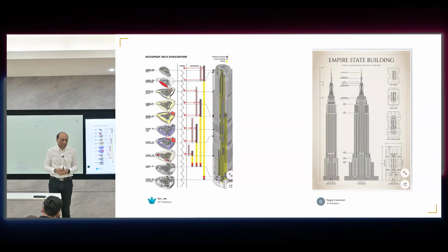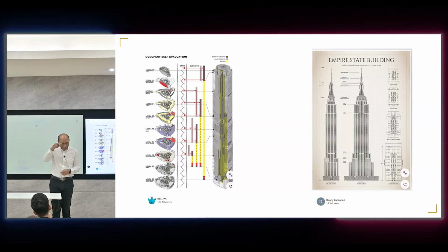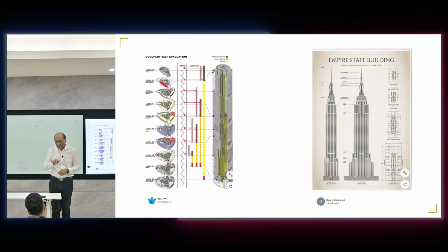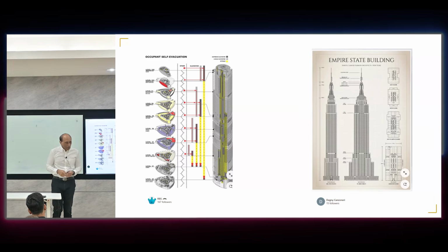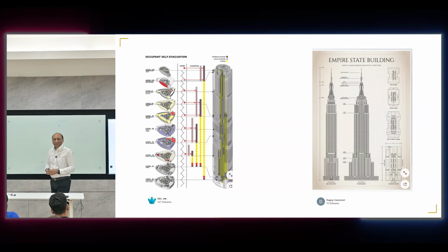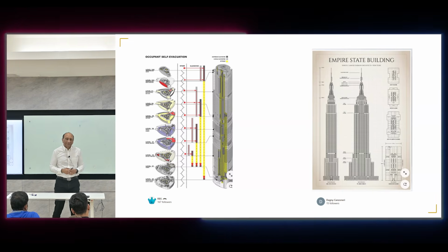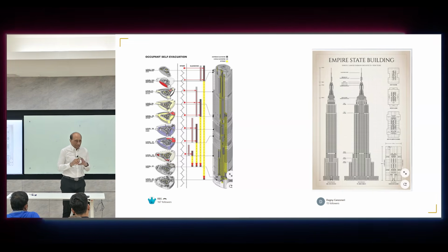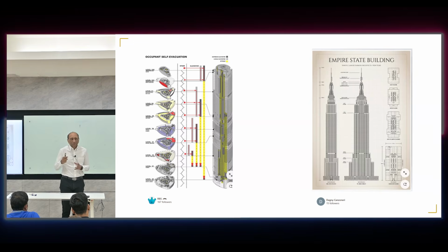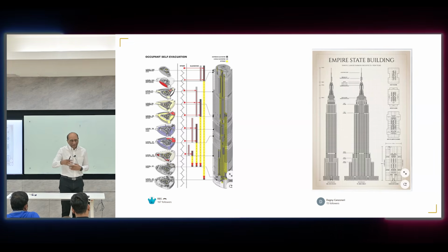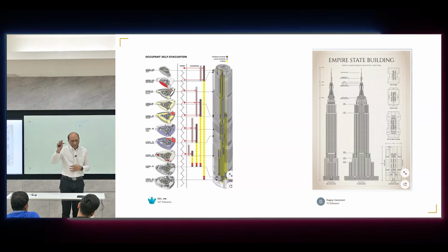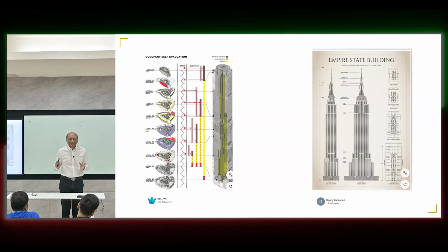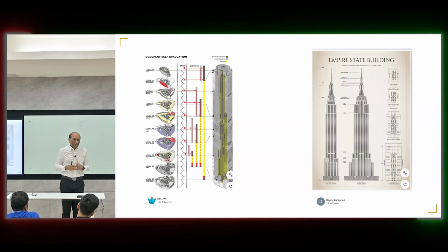So when you enter that evacuation space, even though there's fire outside, it cannot come into that space, and normally you have to come down, and there are tunnels. If you look at the evacuation plan in a real tall building, it is a highly complex and highly technical design of that evacuation space. It's not just normal stairs. There are fire doors, and if you open them, the alarms will sound, and there are two or three levels of fire doors and many things.